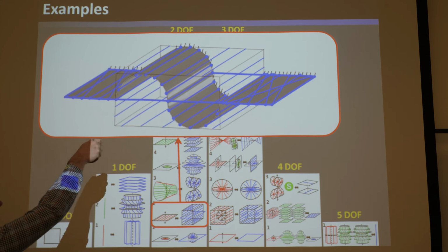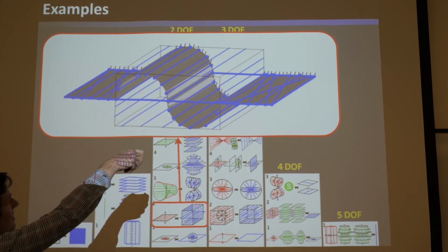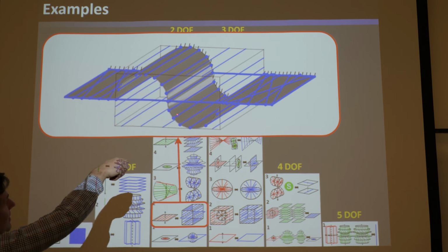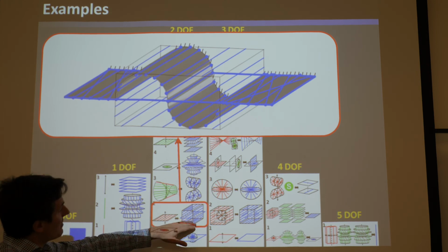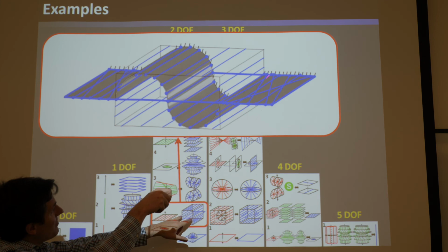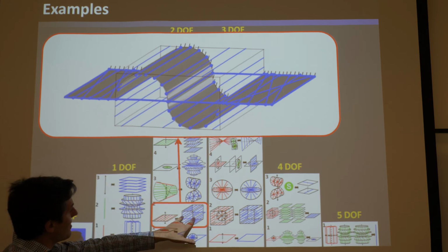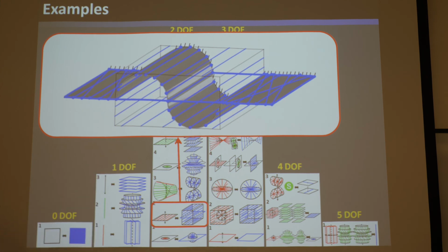But if this back edge and that back edge attached to a ground or a stage, and then this front thing I'm tracing there attached to a stage, then it would be parallel. You'd see this would be basically 2 blades, and this would be a nice curved cylindrical surface where only parallel lines lie on its surface, as long as it's infinitely thin and fairly curvy here. Then you achieve this constraint space where you have the plane and these angled blue lines on both sides, and then these just purely lie in a box. So there'd be an order of constraint of 4, and it would achieve this freedom space.